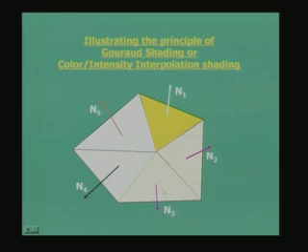There are 5 different surfaces with 5 different shades. I have tried to give 5 different shades; assume some of them could be the same or different, but you compute, and this we know because, given the vertex coordinates x, y, z, you know how to compute the surface normal of each of these, and then take a summation of these vectors and average to get the vertex surface normal NV. So, you do this for this point and you keep repeating this for all the other vertices.